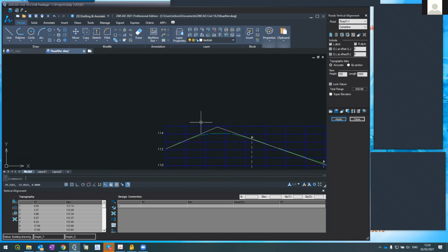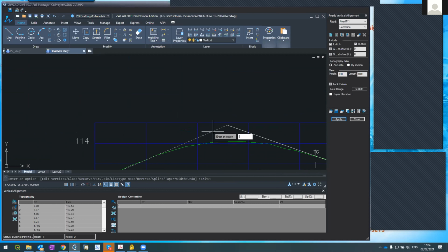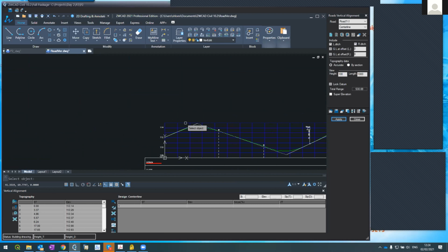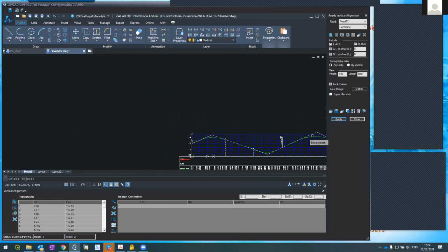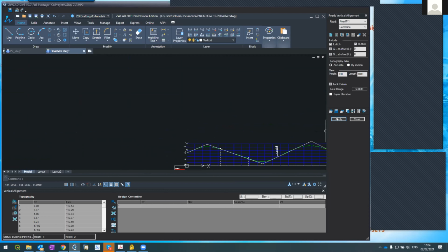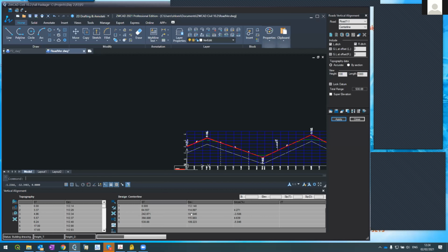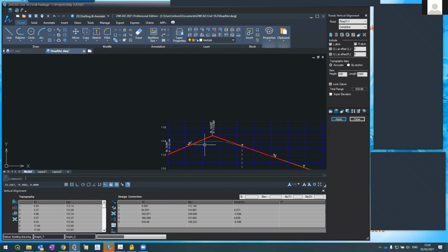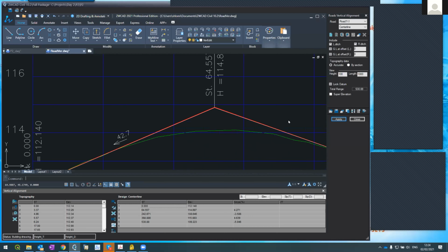Good. And now, since I need it to be one polyline, I do p-edit, this, join, 1, 2, 3. Yeah, let's see. Yeah, it's just one polyline. Now it's one polyline in vertical edit, so I can press apply. And I got my entire road. And the length of the curve, this is, let's say, almost 75 meter. So let's say 73 meter. I can play with it.